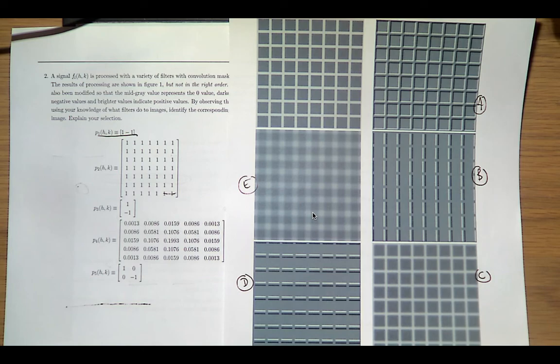Okay, it doesn't necessarily mean it's a high-pass, but in this case you look at the next pixel minus the current one, so you're looking at the gradients of your picture. And so they will pick up the edges. They will look at the strong gradient along the x direction. So you're going to pick up what types of edges? The vertical, the horizontal edges.